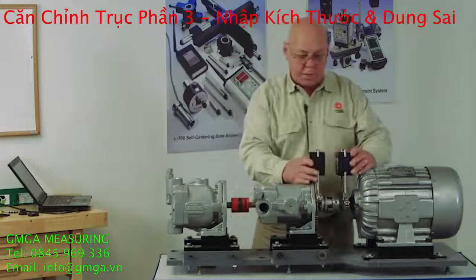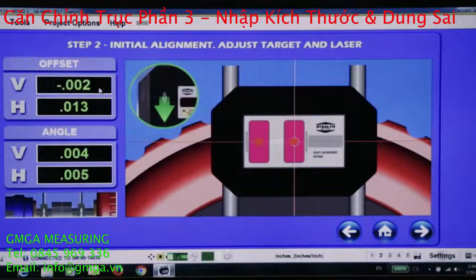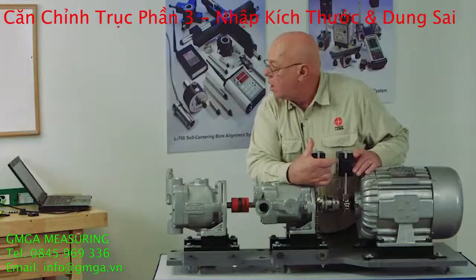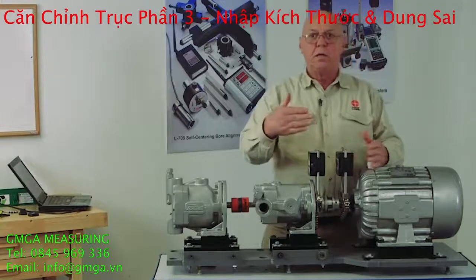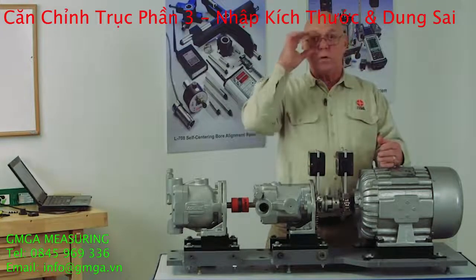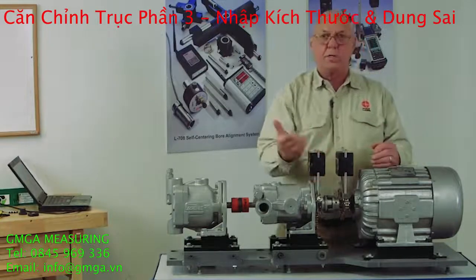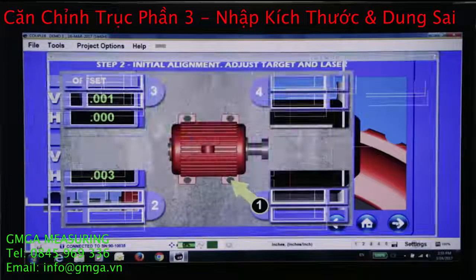Now if this was off sideways, let's loosen it and make it off just a little bit. Now you see, I get a picture on the screen here, tells me to turn that thumb dial down. So if I turn that down until my horizontal numbers come in where I'm satisfied, the arrow goes away. That dial is moving that beam sideways, adjusting horizontally. So vertically, I just loosen the screws and move it up and down. Horizontally, I just turn the dial. So it's pretty simple for course alignment. Go to the next screen.